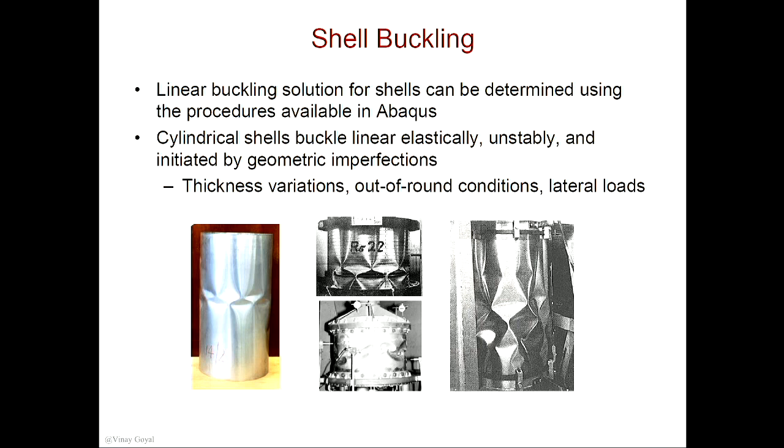And so it turns out that when buckling happens, as you saw here, that's catastrophic. No question about that. I can't really do that to the ruler, right? It's going to take the first buckling mode. It's going to take that shape. It breaks because the strength got exceeded, not because of buckling. With a can of Coke, you can see here quickly how the structure became unstable, right?